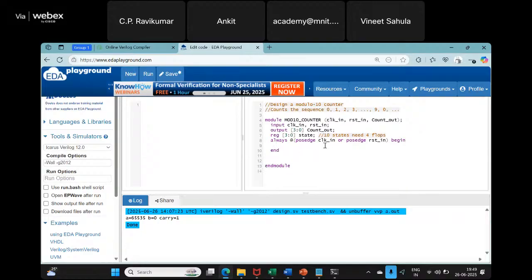And we have to decide how to handle these two, when the reset is triggered and when the clock is triggered. Between the two, reset takes higher priority. So we check that first. So if reset has become 1, that means it has gone from 0 to 1 here because we are checking for this positive edge. Then we have to set state to 0.